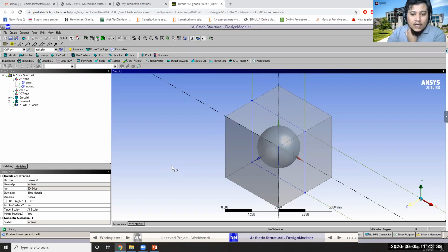All right. So we have a material and geometry that have symmetry, and the material is isotropic as well. We can make use of all these symmetries, and in order to do that, I'm going to only use 1/8 of this cube, because 1/8 of the cube is enough to be representative of my whole cube.